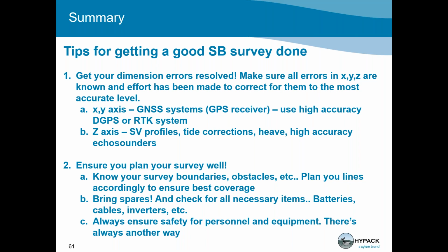You want to make sure that you have a lot of soundings at the seabed, so you shouldn't go really fast. So I wouldn't recommend going more than 5 knots, really. And it depends on the area. If it's a small lake, you can't go 5 knots because then you zigzag across the small lake. So you want to go anything between 1.5 and 5 knots. It depends sometimes on the wind as well, and some currents. They might take you away, so you have to go a little bit faster to stay on the line. But yeah, anything between 1 and 5 knots.